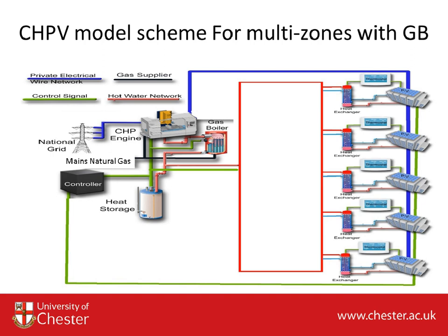It's also very useful for the CHP engine in improving its heat utilisation efficiency. So we chose heat storage, and in this particular case, that was a very large hot water tank. If any of you have been to Birmingham University, I believe that Birmingham University has got a couple of very large tanks, which will please the vessel people, which they can store hot water in for their CHP system.